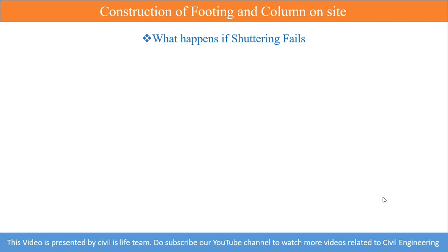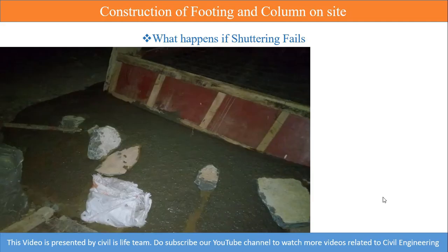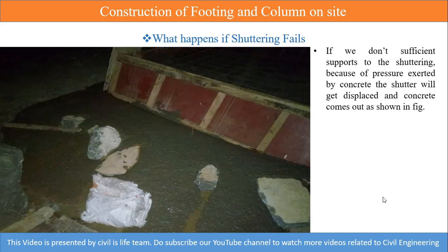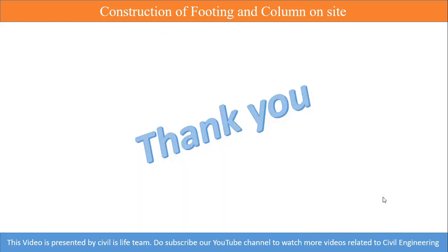So the question is, what happens if the shutterings are not provided with a sufficient number of supports? As I have already said earlier, it will get displaced and the concrete will come out of the footing, and it will be a loss to the company as well as the senior may scold you. So it is better to check all the necessary things before proceeding. Thank you.